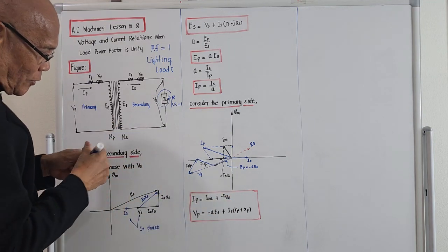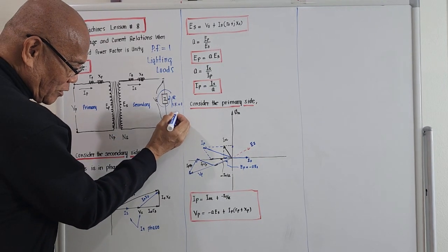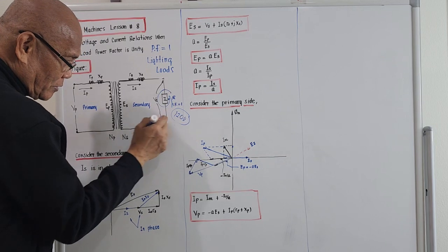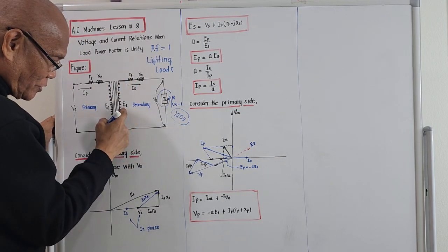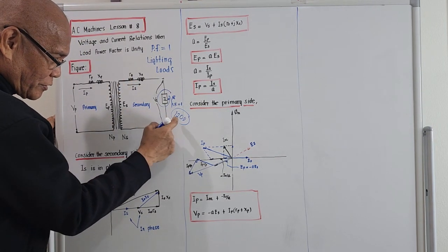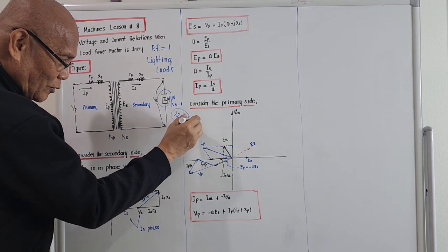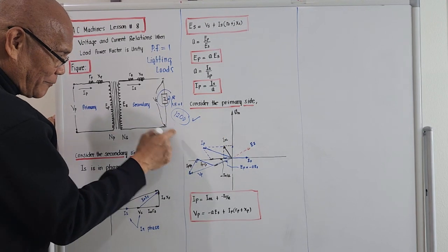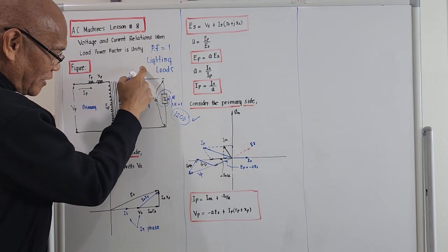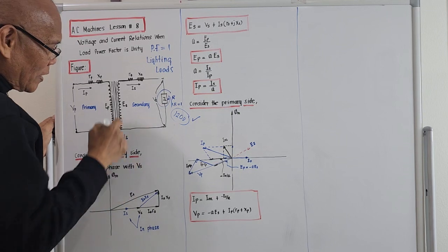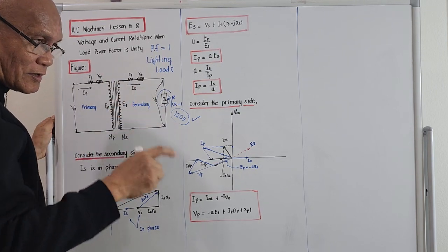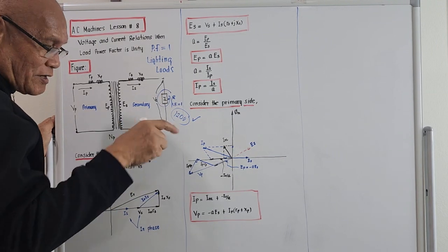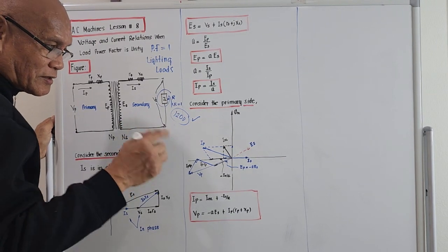So for us to take a value of 120 volts on the secondary, there should be an induced voltage on the secondary which is greater than this to obtain 120 volts. You got it? Why? Because there are the so-called R_S and X_S effects. R_S is the internal resistance of the coil, and X_S is the reactance of the coil.